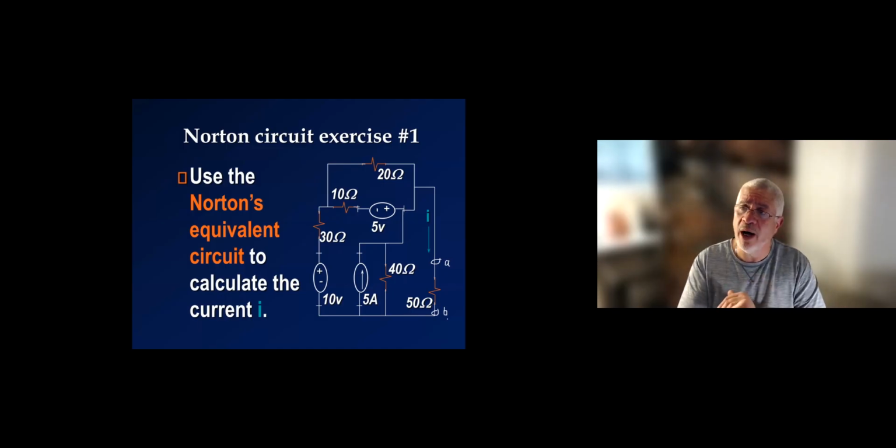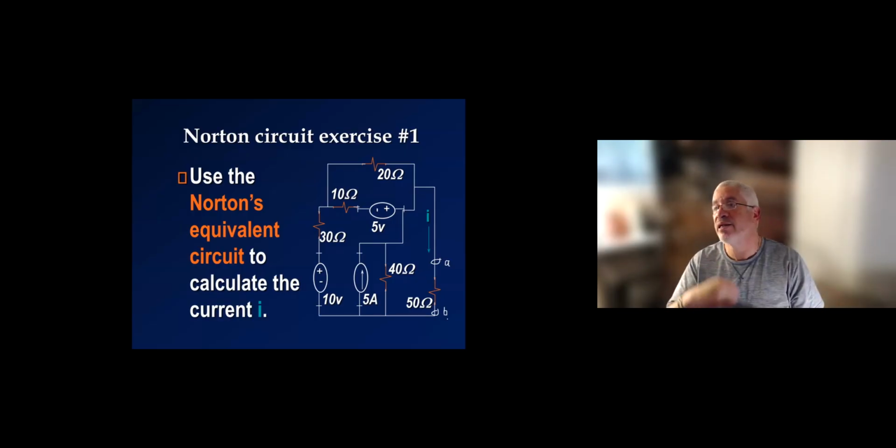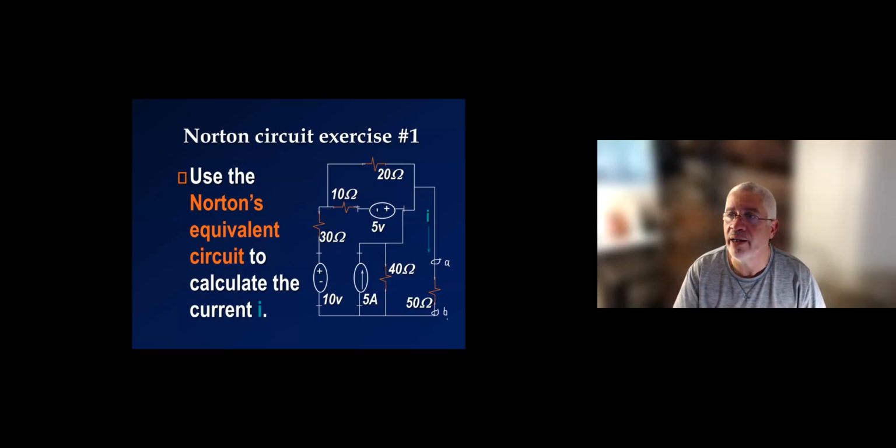Again, when we talk about the Norton model, we are talking about what the model schematic is. That is a practical current source model. The independent current source is ISC. The resistance is the Thevenin resistance in parallel with the independent current source. And then you proceed to calculate ISC and the Thevenin resistance, and then you come back and answer that question. So please pause the video and then restart it whenever you want at that point so that you can look at the solution. It's crucial that you actually do that work instead of watching me do it.